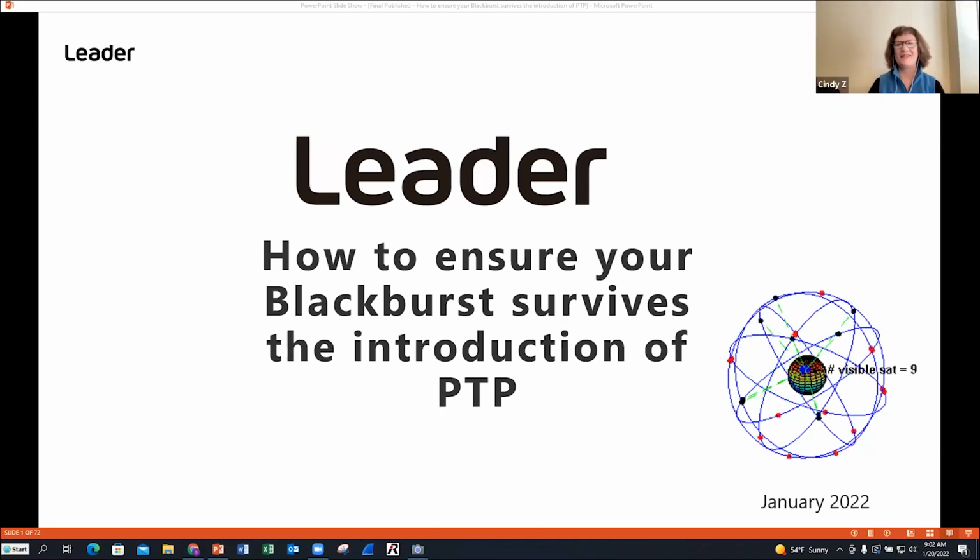Yes. All right, well, we've all grown up with Blackburst reference in our facilities, right? And the only change we might have had to manage is the introduction of tri-level sync when facilities started migrating to HD. Now, expansion of Blackburst and tri-level sync reference systems was relatively simple. Either daisy chain the new device with the loop-through genlock output from an existing device, or use a distribution amplifier to split the BB/TTL reference signal. What could be simpler?